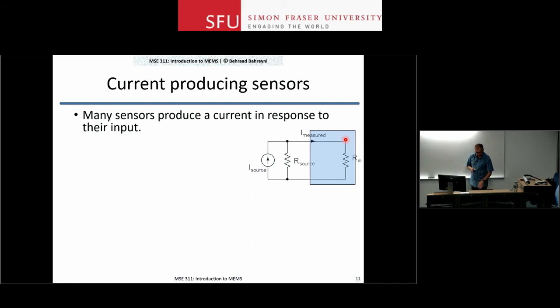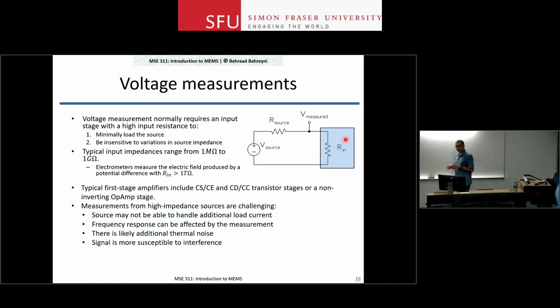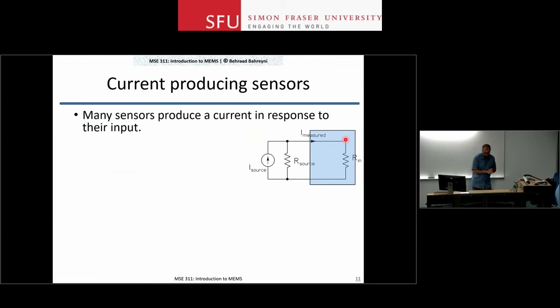Okay, so coming back, when you have a high impedance sensor, be careful. A large input resistance is your friend when you're doing voltage measurements, but be careful. Again, a large input resistance can do some damage to your system as well, or to your measurements as well.